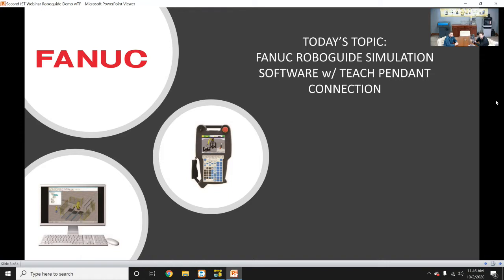But there's actually 3 clicks when you squeeze this dead man switch. And students have to learn that they actually have to hold that in the middle. And it's something that, again, it's familiarity. They have to make sure that they understand that that's the process. That safety mechanism that's in place, if it's compressed fully, the robot will actually get a message that says, okay, something might not be right here. We're going to stop. Or if it's completely depressed, it sends that very signal. Again, holding it right in the middle is where students have to get acclimated to understanding that's where they have to be holding it in order to operate a FANUC robot. So, again, those are just some of the perks of actually having this thing in their hands and taking away that foreign feel when they actually get up to a robot for the first time.